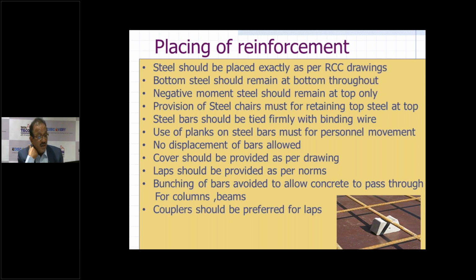Then you have to use planks on the steel bars when personnel are going to move. People are going to move while the concreting process is happening on the slabs or whatever. At that time, you should not allow people to directly walk on the steel. There should be wooden planks placed on the steel bars so that the bars are not damaged and people are also not getting injured. Then the concrete cover blocks should be provided as per the drawing.